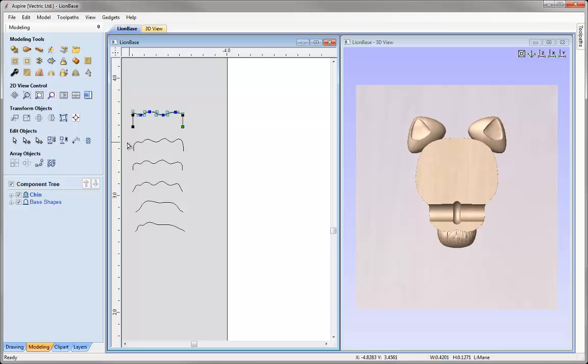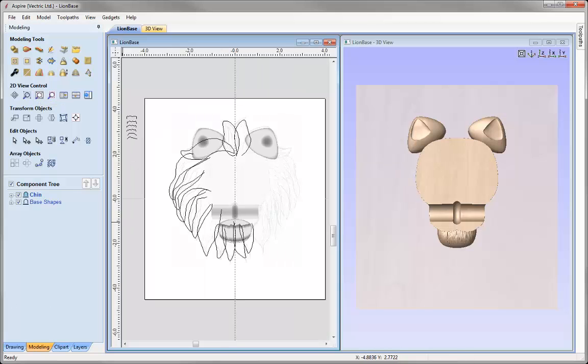We'll use this icon here and we can see how the shape of the vector is formed. Okay, so I've got lots of different cross sections. I've got wavy ones, lots of waves in ones, and then I've got vectors that slope down and have less waves within. The reason for that is just to give a lot of diversity in the shapes that we're creating. So let's just use this option here to zoom to fit.